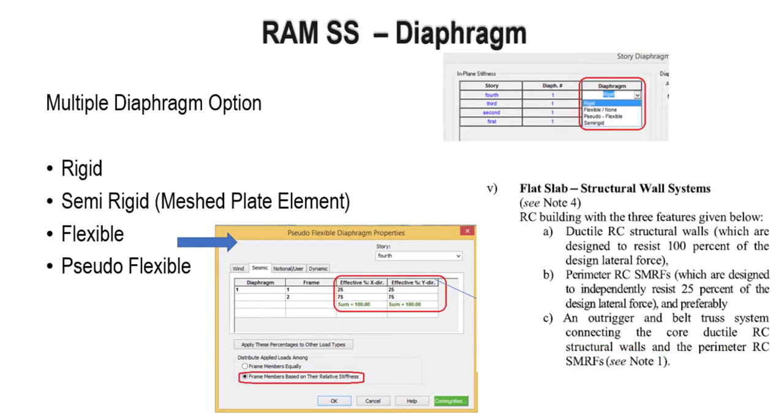So the question is, rigid or semi-rigid? That's a very vital question. Which type of diaphragm should we take? The answer is not that straightforward. There are a lot of advantages if you take it as rigid, and even if you are taking semi-rigid, you can also get some benefits. But both of them have some shortcomings, so we will see it. Depending on that, you have to apply your engineering understanding and discretion to select the type of diaphragm which is needed for your structure.